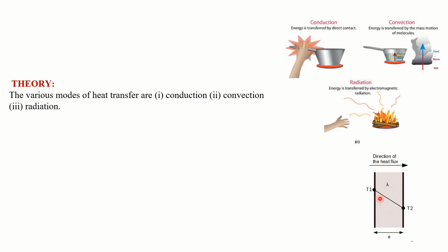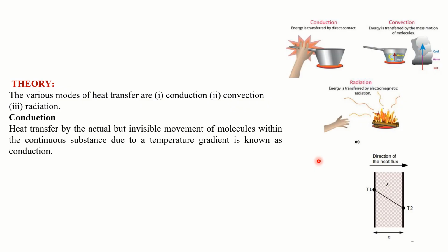The molecules with higher energy will impart energy to the molecules having lower energy. So due to the movement of molecules, heat will be transferred from the inside surface to the outside surface, that is, from the surface at a higher temperature to the surface at a lower temperature. So conduction is the actual but invisible movement of molecules through a solid substance due to a temperature gradient.